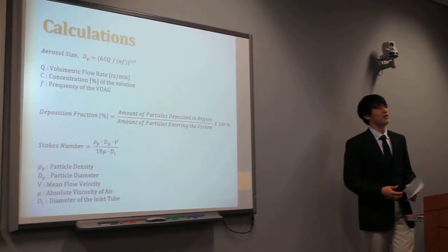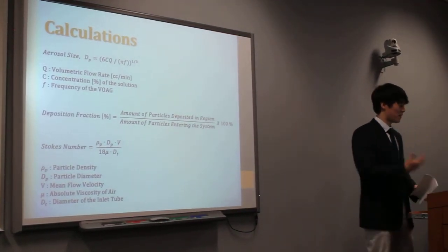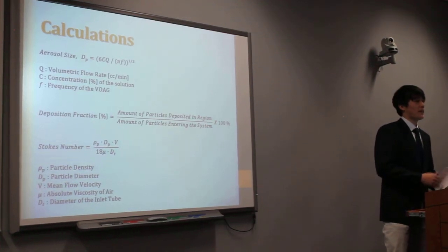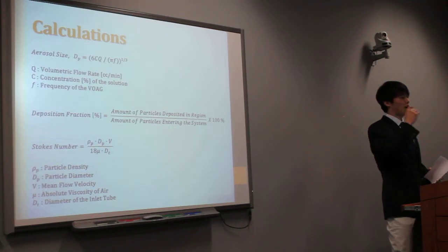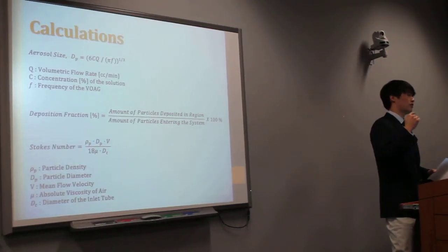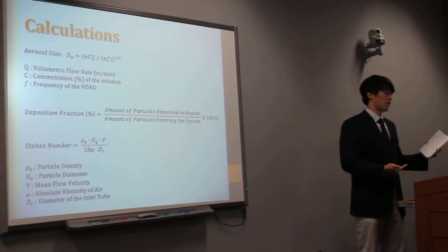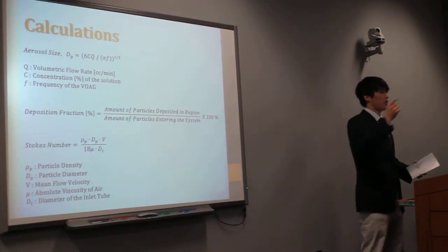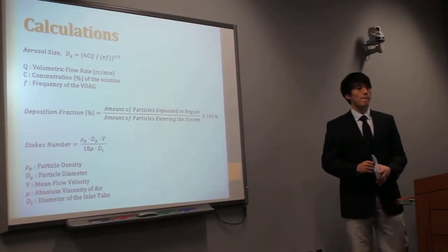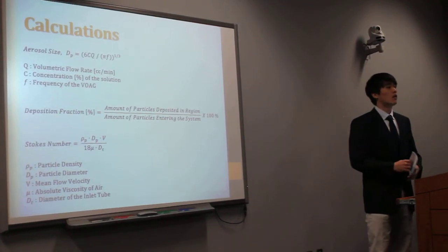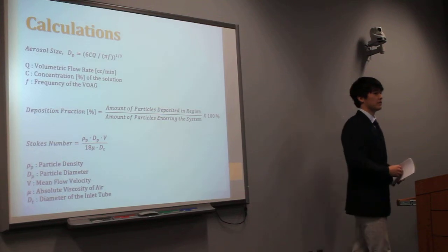So if it has a high Stokes number, it's highly predicted to follow the initial trajectory of the aerosol. While if you have a low Stokes number, it will just follow the streamline, no matter what the initial trajectory was. Isn't it a ratio of two forces, like the ratio of the inertial force to the shear force? Yes.